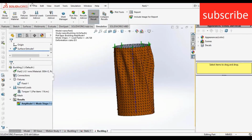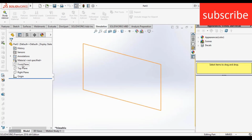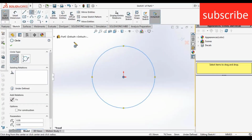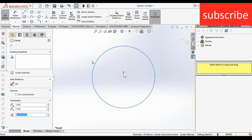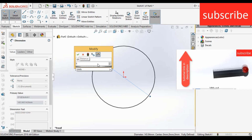So first thing we need to do is create a part. Click on new, click on part, click OK. After that click on front plane, right click on it, click on sketch. Now draw a circle of diameter 55 mm.